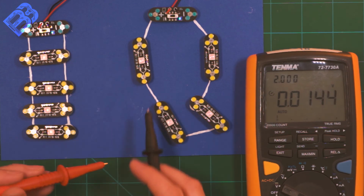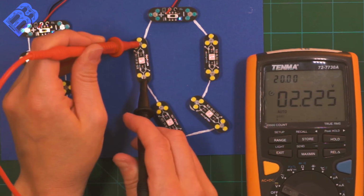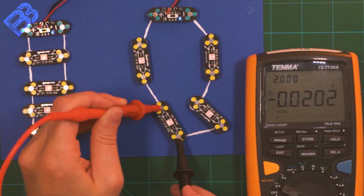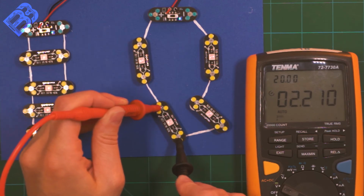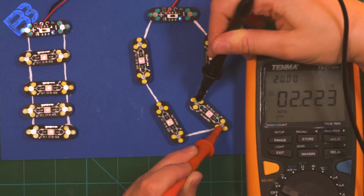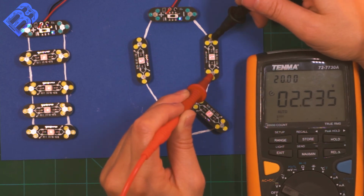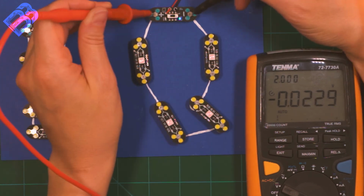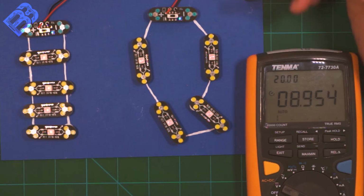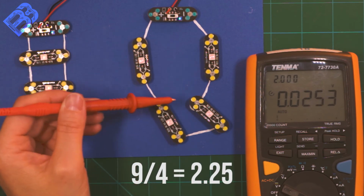In comparison, let's check our series circuit. The voltage across our first LED is 2.225. Across our second LED, again, we have about 2.2. Across our third LED is 2.2. And across our fourth LED is 2.2. On this side, the voltage supplied by our battery is around 9 volts. If we take 9 volts and we divide it by 4, we get about 2.2.